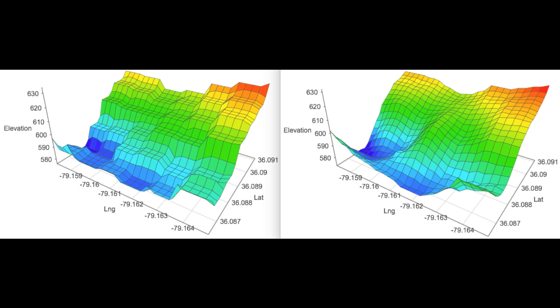The system also works in altitude above ground, or AGL. The server builds a three-dimensional map of the terrain. The drone can be switched into a mode where it flies at a constant altitude above the terrain. This lets the pilot fly the grid centers and look for people and not worry about any terrain changes that might happen.